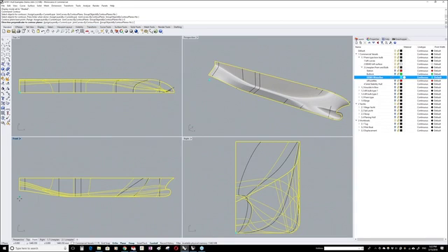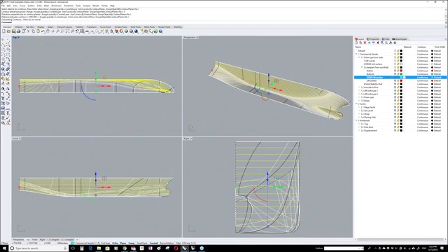And then it asks me for the direction perpendicular to the contour planes. Well, I want waterlines, and the direction perpendicular to that is the Z-axis, so I point upwards. Then it asks me for the distance between the contours. My model is in millimeters, so if I type in 1, I will get millions of waterlines. That's not something I want. 1 meter is a nice distance, so 1000 is what it is showing here, and I accept that. And there are my waterlines.